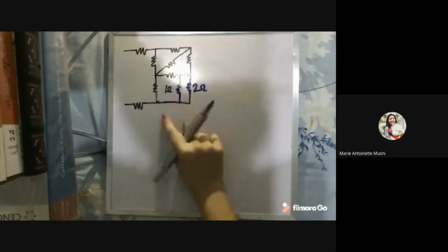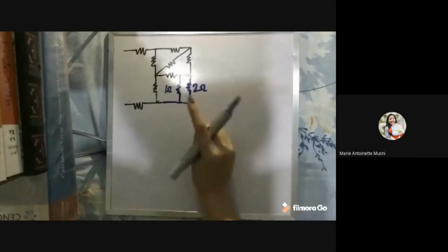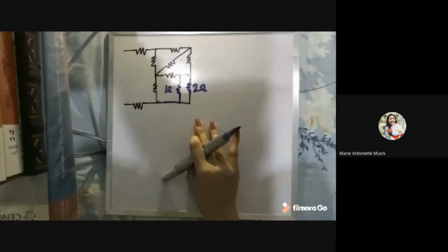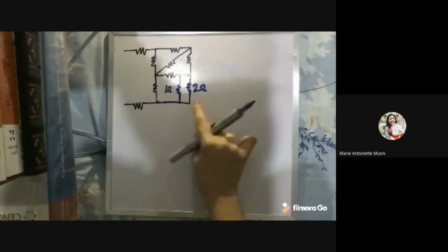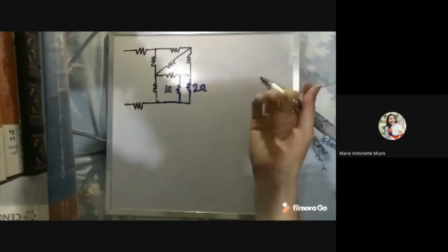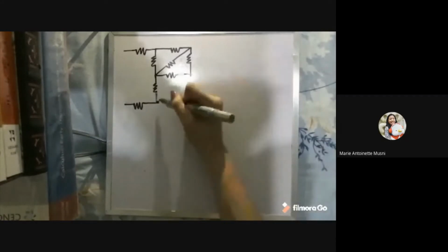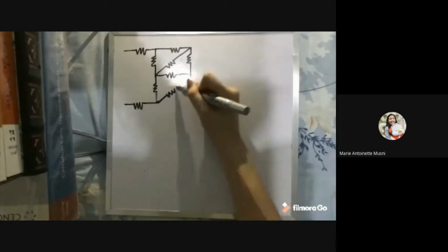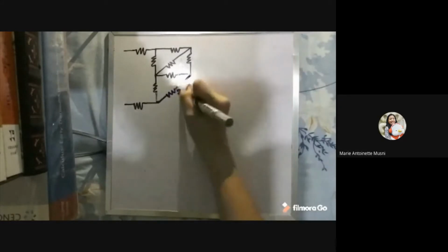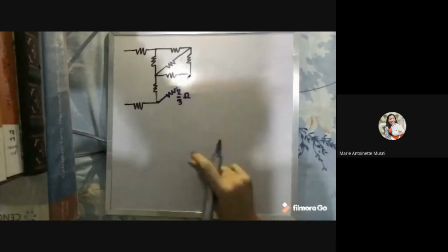Now, for parallel circuits, we get the sum of their reciprocals and raise that to -1 to get the combined resistance for the combination. So that's (1 plus 1/2) raised to -1. We're going to get a value of 2/3 ohms. Okay, let's remember that it's 2/3 ohms, and we can redraw the circuit to have our 2/3 ohm combined resistance here.